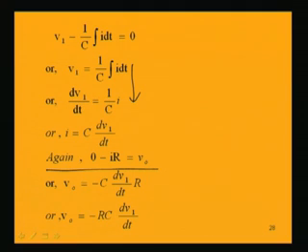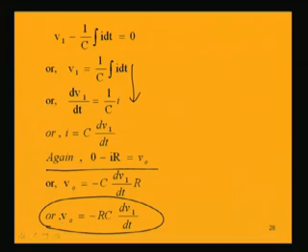From the second equation, we get what is V naught? V0 is equal to minus IR. Now, minus I can be replaced from here, C into dV1 by dt into R. So, V0 is equal to minus RC dV1 by dt. If we look into this expression, this is nothing but differentiating the voltage V1. So, we get a differentiation of the signal V1 by this connection of this op amp to the resistance and capacitance in this way, and in the earlier case we were getting an integration operation.